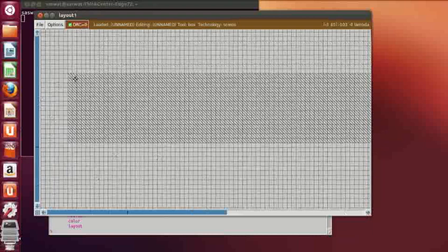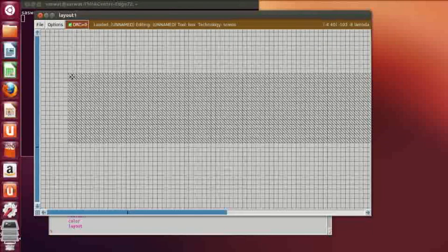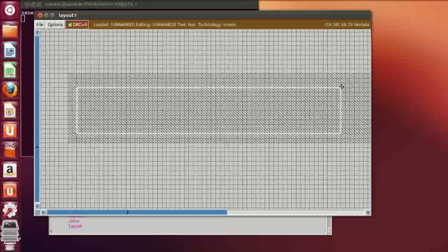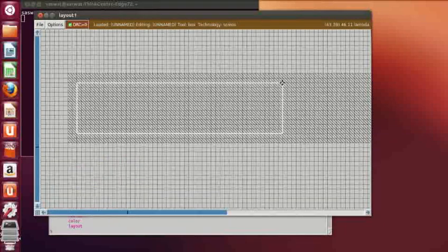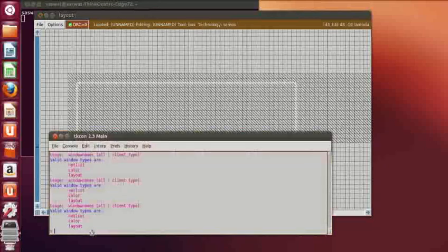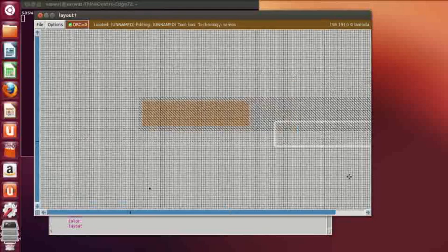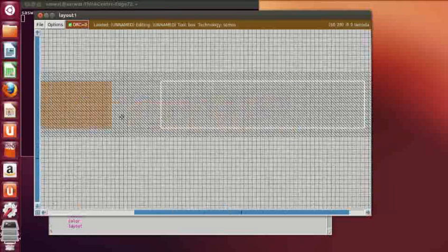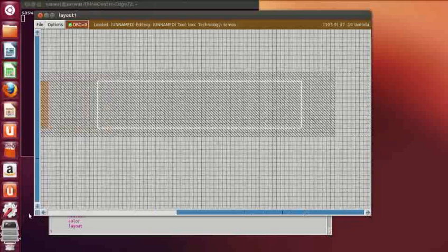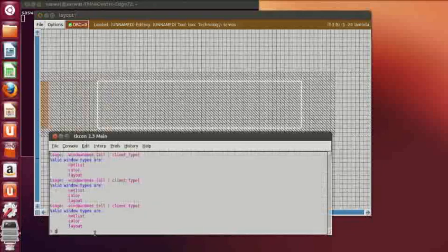Now after painting this N-well, the two PMOS, that is the first and the second PMOS, have a common drain. So we can draw like this for two at a time, or we can even reduce this area up to this much, and then type paint pdiff, that is the p diffusion layer. After this, we can place it over here. We will leave some more space so that if we need to extend this, we can extend it freely. Then type paint pdiff.